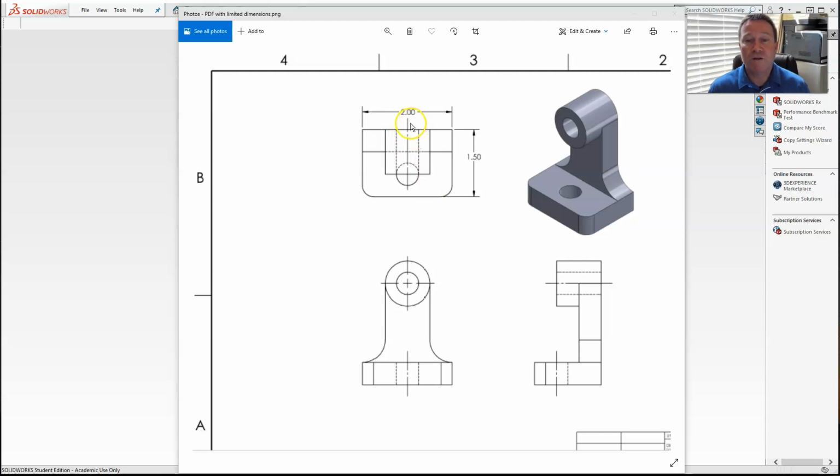Pick our part origin to correspond to an origin on these pictures, and then build off of it. When we extrude or cut, you can grab the little arrow and adjust your extrusion length visually, and we can use the lines when they're placed on different planes to actually extrude to those lines.